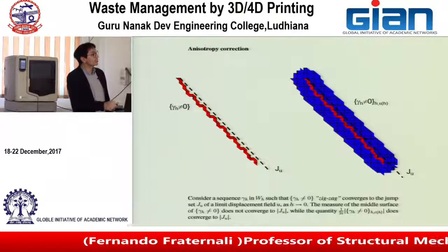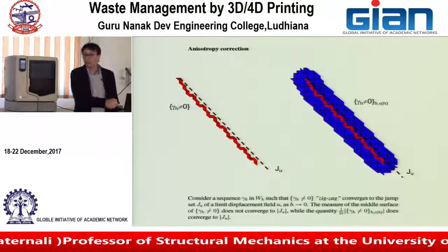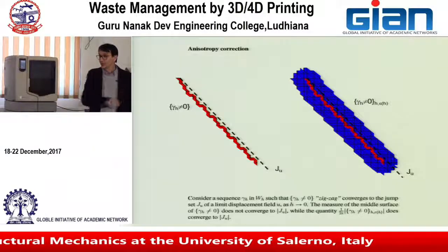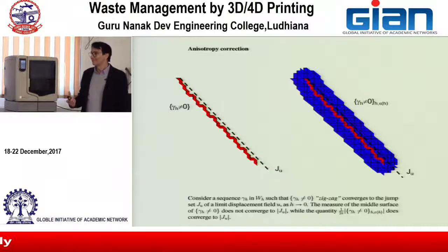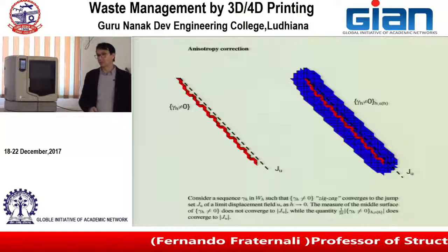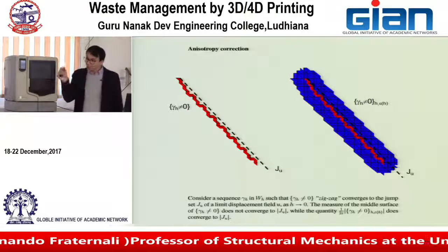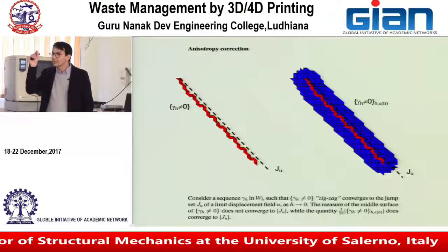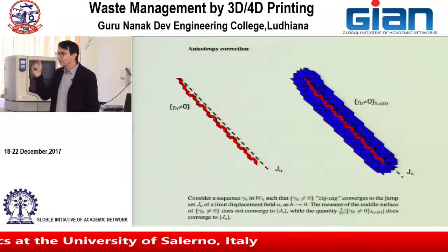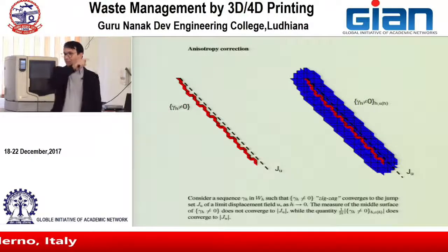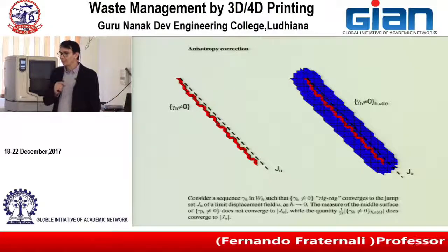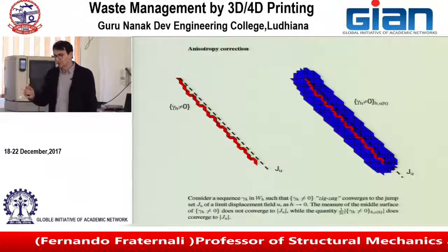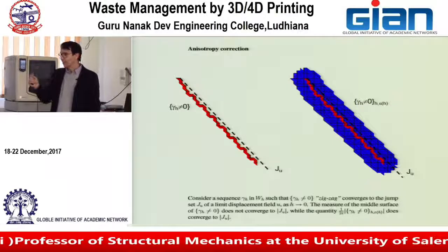So the measure of the center line is not equal to the inclined line. You get a prediction that is mesh dependent. You can take the mesh size as small as you want, there will always be a difference between the length of this zigzag line and the straight line. So this approach will not converge when you use very, very fine elements.